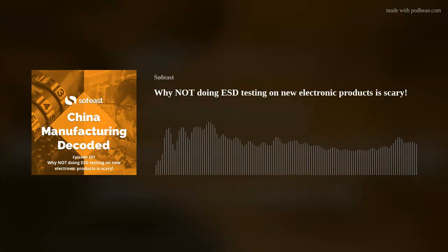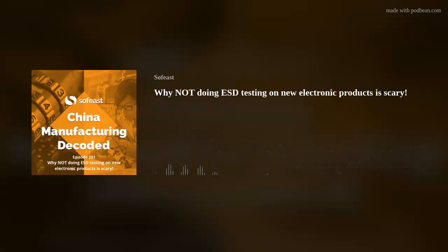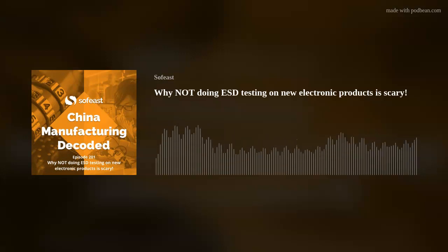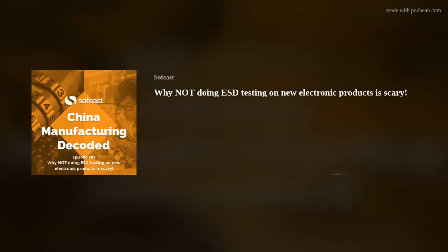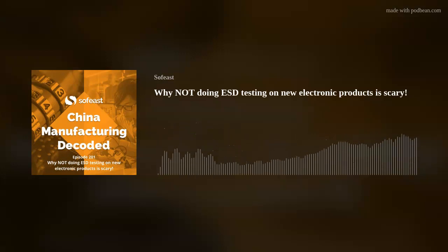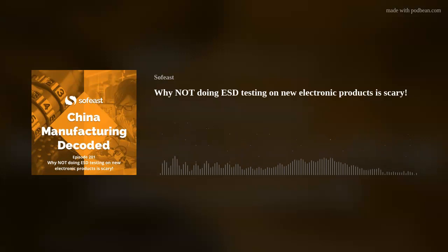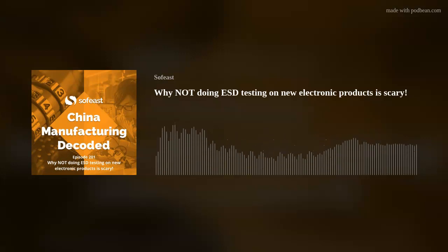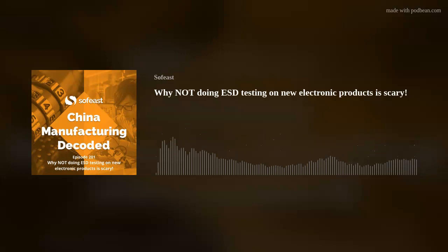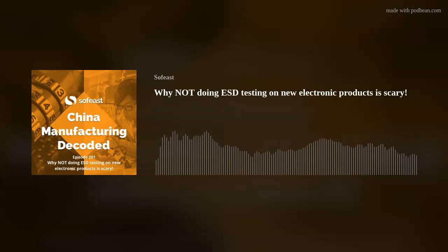But if we just wrap up then, and then I think we're good, because that's been a really good overview, Andrew. Yeah, I think just as a wrap up, I would say for most experienced design engineers and manufacturing leaders, they know what is required when it comes to ESD. But just in case someone forgot about it, during the design and development phase, make sure all your workstations and test stations and engineering labs are ESD protected. And when you are designing your product, look at the data sheet and see whether there is an ESD protection requirement. For example, you may need to design a certain electronic circuitry to protect your IC or your design from ESD. So you need to be aware of that as a designer.